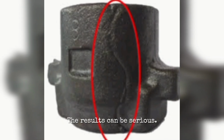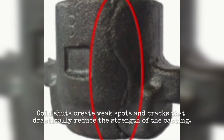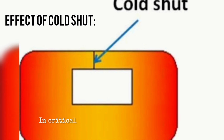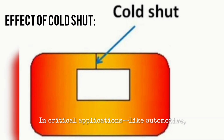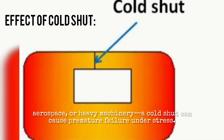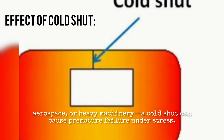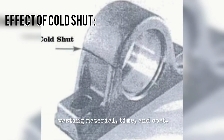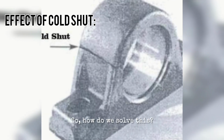The results can be serious. Cold shuts create weak spots and cracks that drastically reduce the strength of the casting. In critical applications, like automotive, aerospace, or heavy machinery, a cold shut can cause premature failure under stress. Even in less demanding parts, a cold shut is often a rejection factor, wasting material, time, and cost. So how do we solve this?